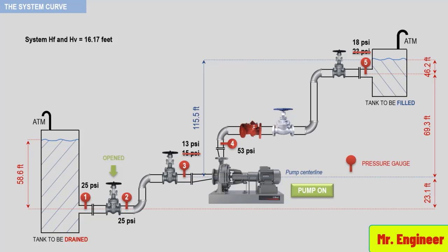Remember that the other resistance approximations, so the Hazen and Williams formula and the Darcy formula, are only valid in the first few hours or days of service. The system begins to change once the pump is turned on and production begins. Operators open and close valves to meter the flow through the pipes. Filters and strainers begin to clog. Inside pipe diameters form scale. Or new equipment is installed or other changes occur with maintenance. So the equipment loses its efficiency.